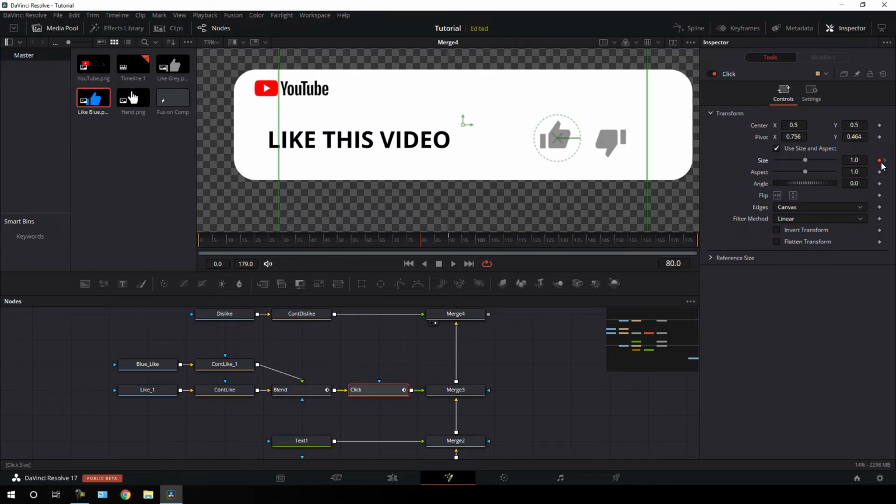Add one more keyframe and lock this value, and go 10 frames forward in time from frame number 90, and add one more keyframe and lock this position as it is, and go to the center of these two keyframes on frame number 90, which is equal to 3 seconds according to 30 fps, and let's bring the size down a bit. So I'm going to set this value 0.8, and now this is a linear animation, so we have to make this animation smoother.